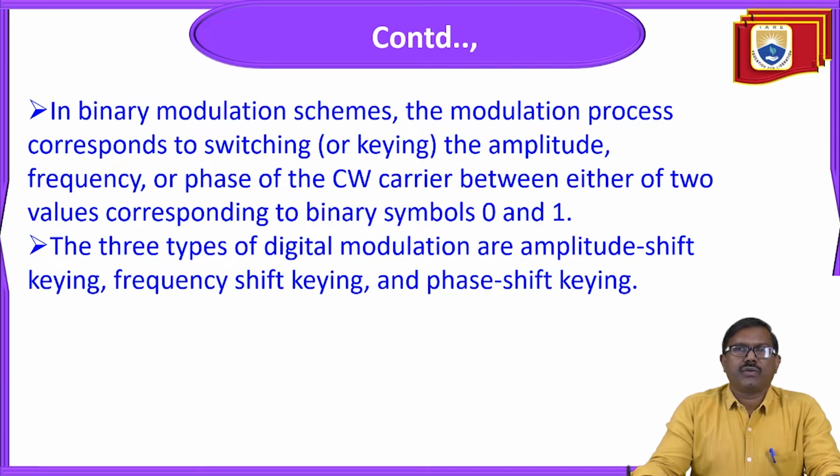You know the term modulation. Modulation means varying some characteristics of the carrier signal in accordance with the instantaneous value of the message signal. That is the basic definition of modulation. In binary modulation schemes, the modulation process corresponds to switching or keying the amplitude, frequency or phase of the continuous wave carrier between either of two values corresponding to binary symbols 0 and 1.